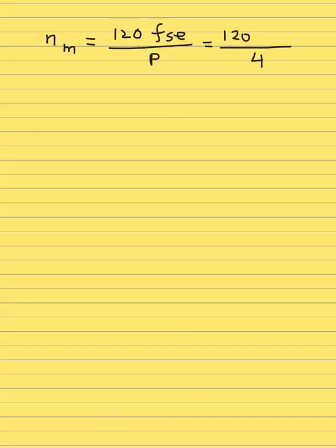And what is the frequency? The frequency it is running or producing the electrical supply at is 60 hertz. So substituting everything together, it gives you the speed of rotation of the generator, 1800 RPM. So the first part of the question is very simple, and that's it.